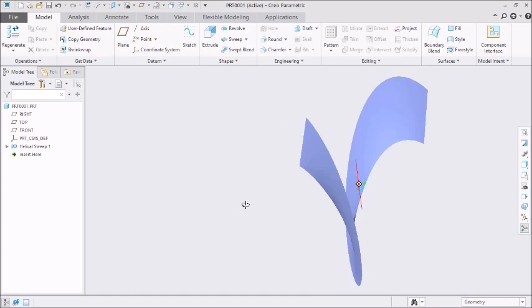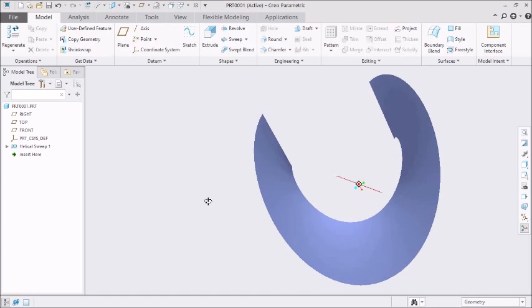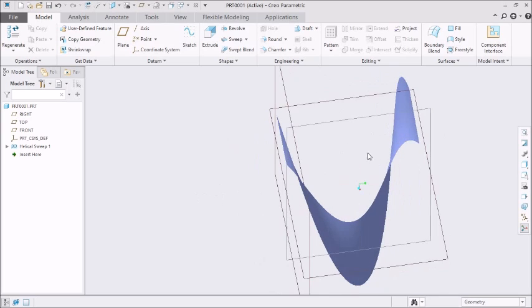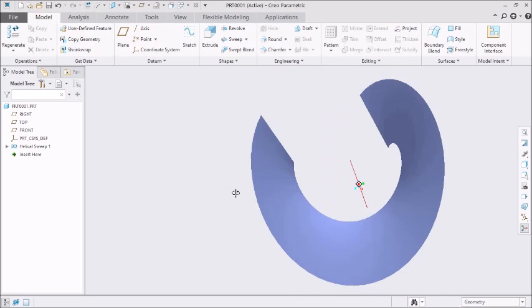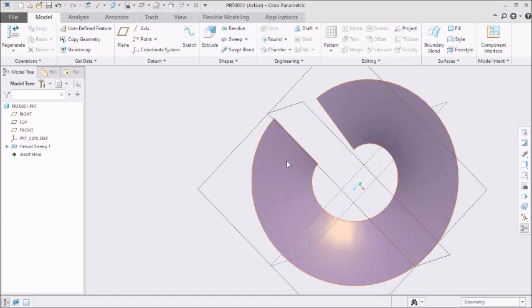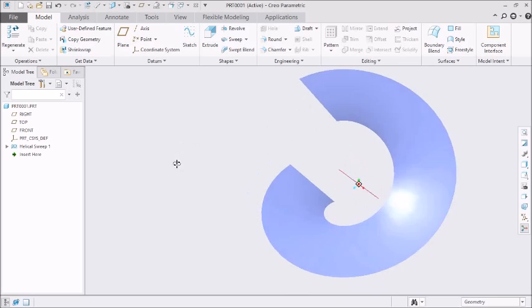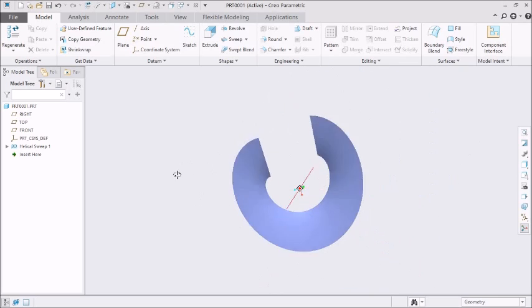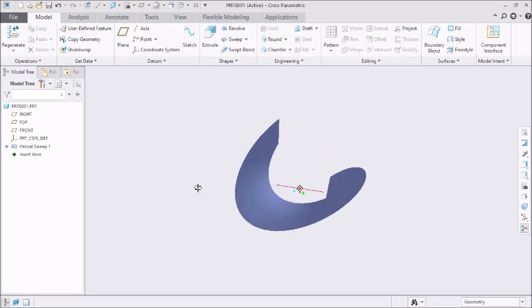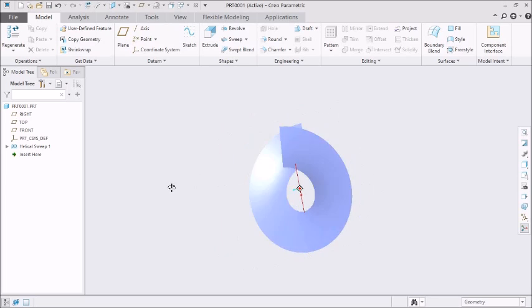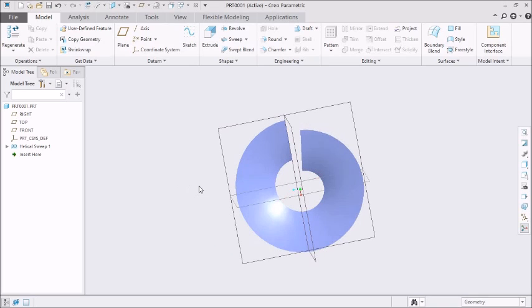Now this helix is going to be the final form that I will be requiring, but before I create this helix I have to cut a blank. So for cutting the blank I need to flatten this out, and then I will have to get the DXF file which I can use for any cutting machine, say laser cutting or plasma cutting or any other cutting operation that one may prefer.